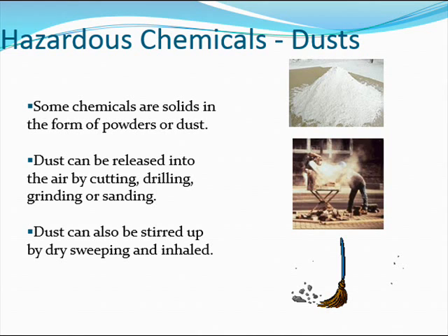For example, cutting a brick or a cinder block without water can generate lots of airborne dust that may contain quartz. Dry sweeping can do the same. If silica dust is inhaled, it can scar lungs and cause breathing problems.